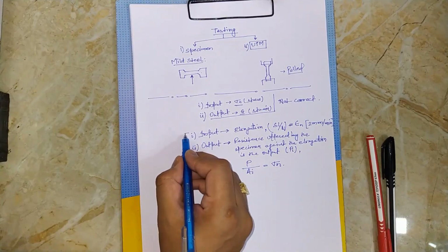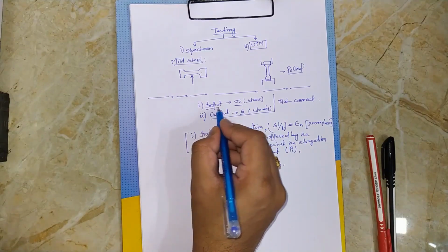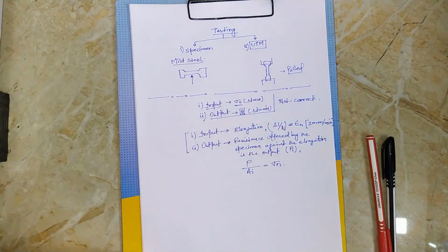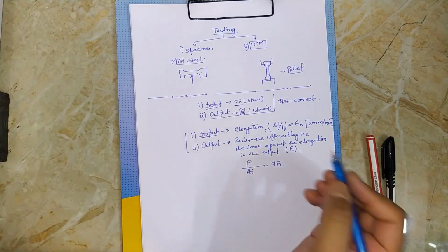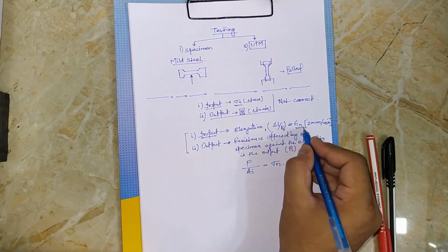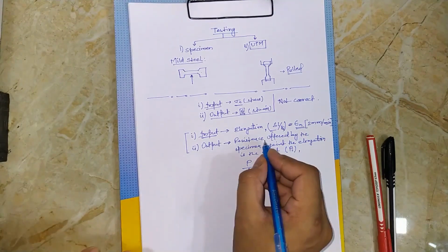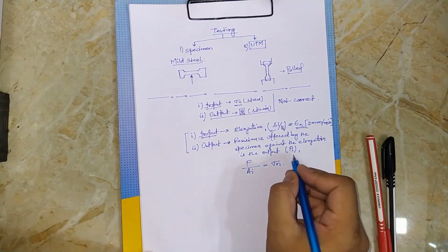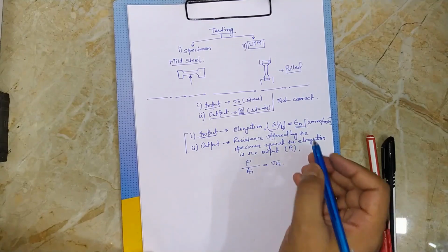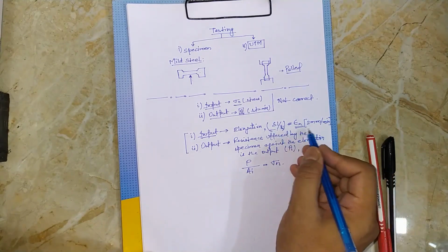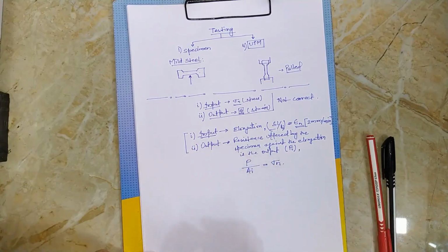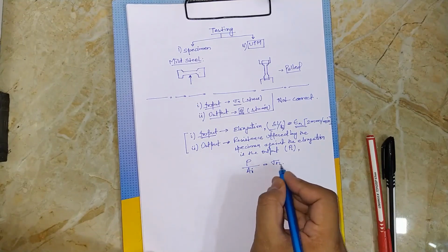I told you that people may have this confusion that we give stress as input to the machine and take strain out of it, but that is not correct. The input given to the specimen by the UTM is strain or elongation, against which the material offers a resistance, which is plotted on the y-axis. So we simply rationalize our coordinate axes by dividing by constants. When elongation is divided by the initial length, we have strain, and when the resistance offered by the material in terms of load is divided by the initial cross section, we get stress.